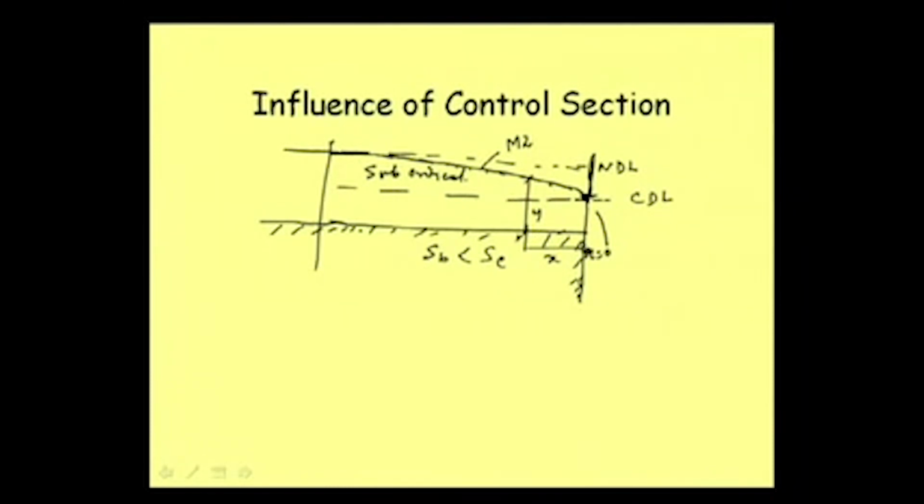And then we can stop computation when y approaches yn. Of course, exactly at yn we cannot go, it will be uniform flow, so we need to stop it when it is just a little less than yn. Well, this is the condition of flow when it is subcritical flow, and that is what we are talking about, control at the downstream point.